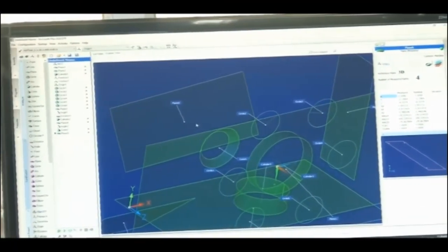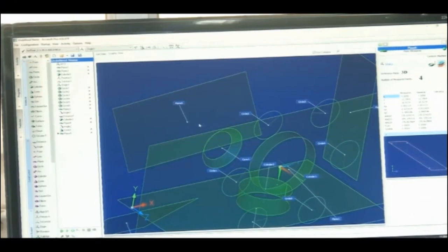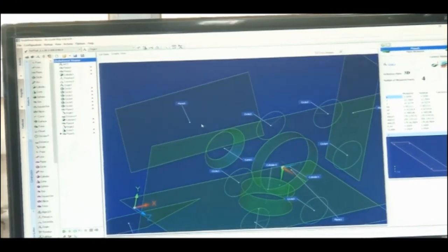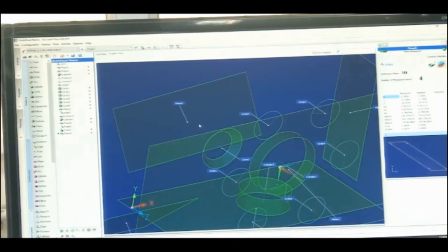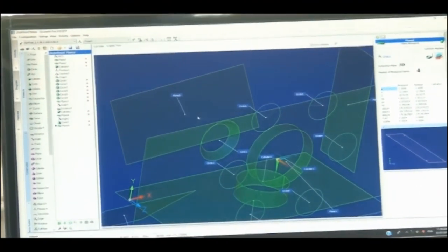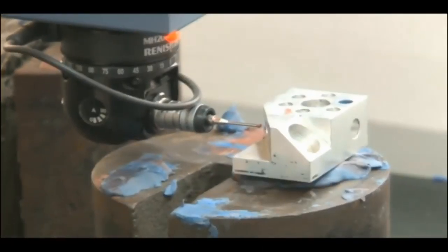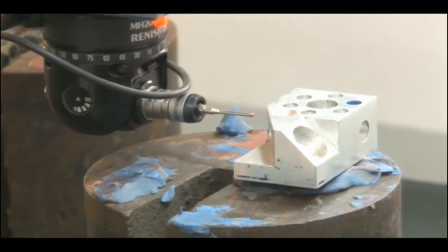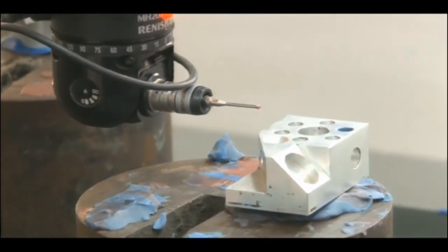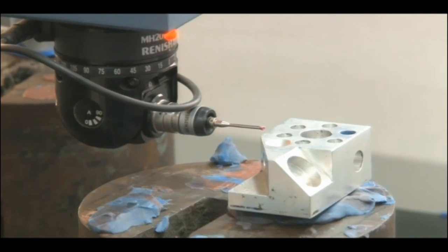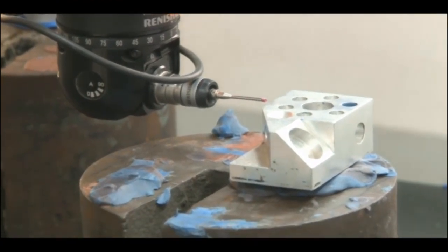Okay. Now, this is the potential or the beauty of the CMM, that by using a single setup we can measure all the parameters in different directions. This is a structure of the known parameters, cylinder, cone, all those things. Also free form can be measured. Okay. So, we can store the data files in IGS format. So, all these parameters can be exported, then we can save it to the file, all those things can happen.